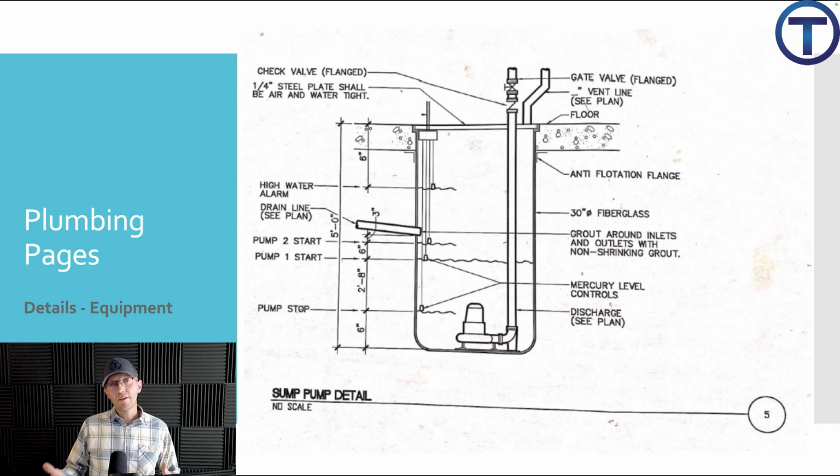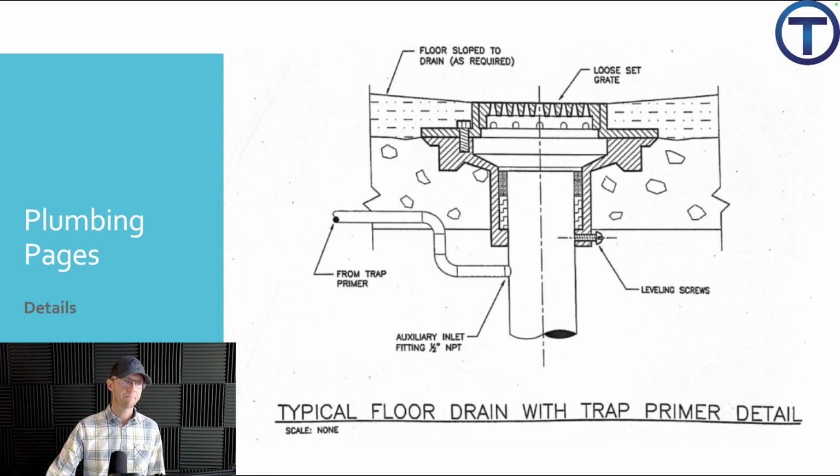All right, from here in this presentation, I'm going to go through a series of details. We're going to go a lot faster than we have on these last few where we really took time to examine them. Feel free to pause the video at any point if you want a better look at this or if you need more time to examine. But here's what we have. This detail shows us the sump, the pump, the different controls, the alarms, the pipes coming in, the pipes going out, the vents, and all of those details that I would need to make sure this is installed correctly.